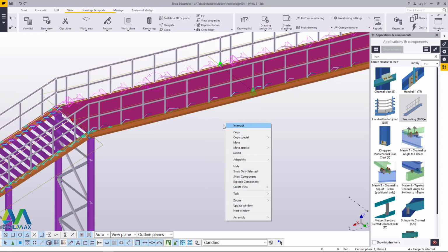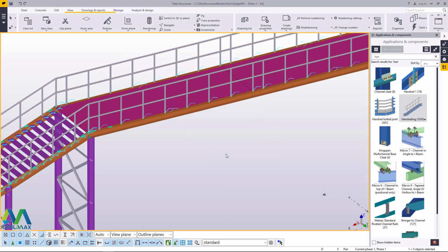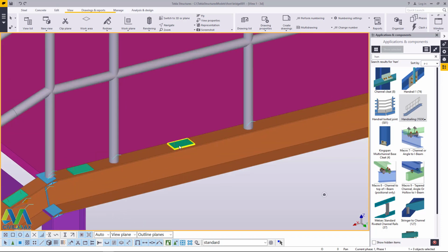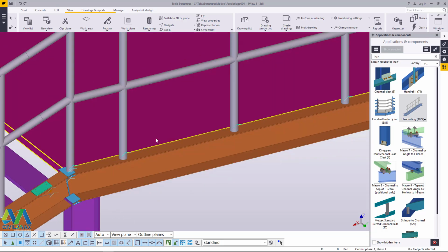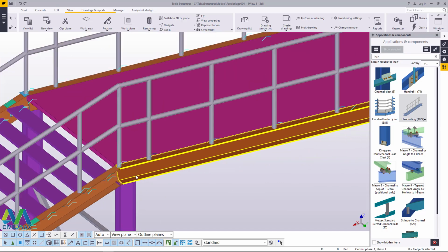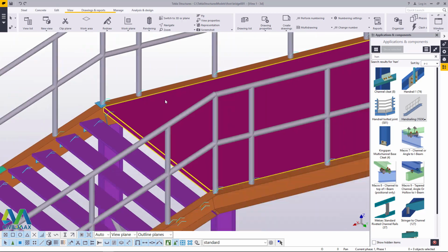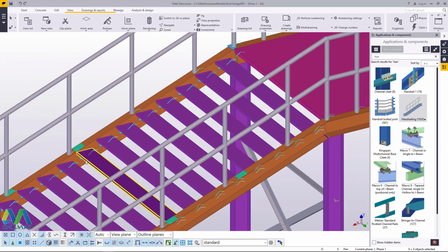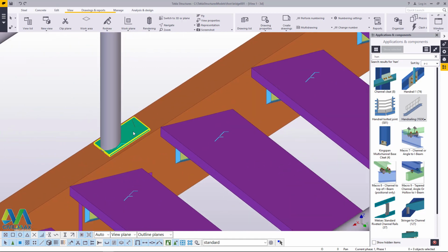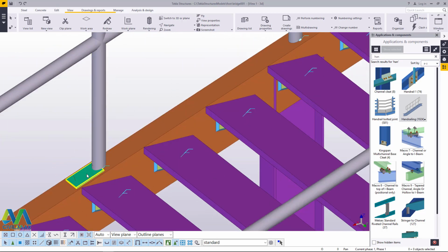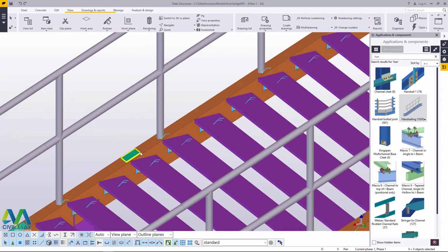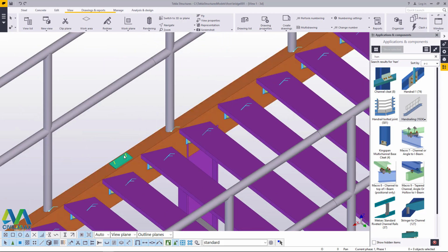What I'll do is right-click on an empty screen and redraw, and this will refresh and clean any unwanted components on our model. I'll get rid of this and get rid of this, and this has been done several times, so it should not be hard to do. I've shown you how to get rid of this by clicking on it individually, because we are using a macro that has its own default settings and components in place, so you have to get rid of the defaults and place your customized design.